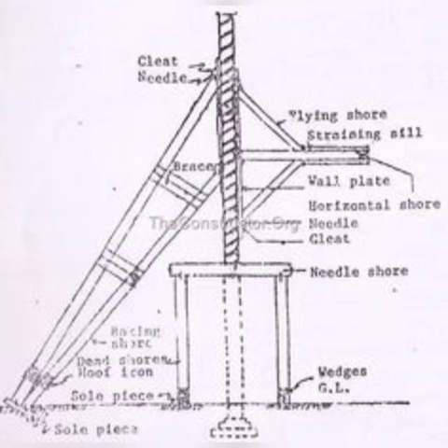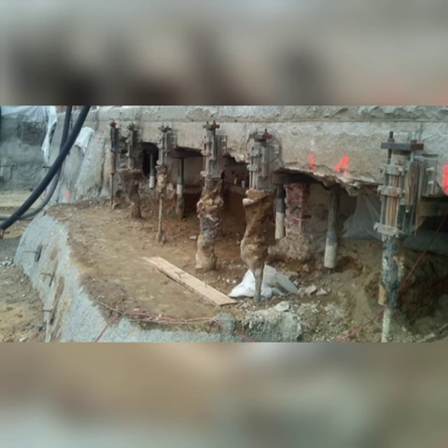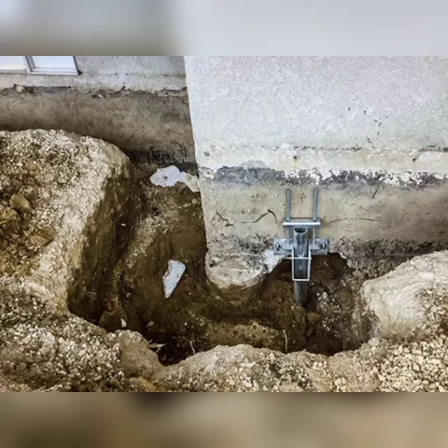Dead shoring support system. The next is underpinning. This system is usually provided when the foundation has to be given strength and also to carry out the repair and alteration of the structure. This is done to improve the bearing capacity of the soil. For example, in order to provide a basement for an existing structure, this method is used.